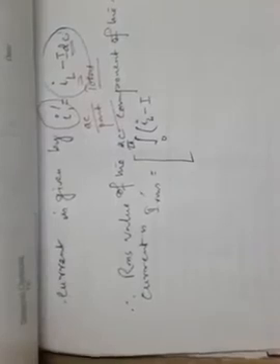So 0 to 2 pi, once again it is a periodic function taken at the input of the rectifier, IL minus IDC, because we are considering the instantaneous AC component and finding its RMS value based on this expression.